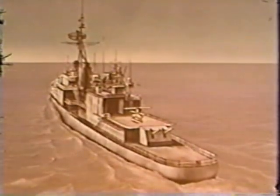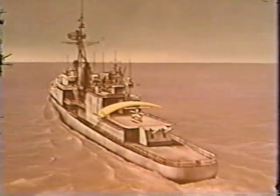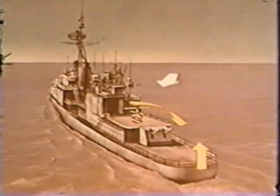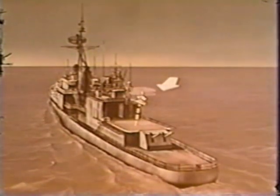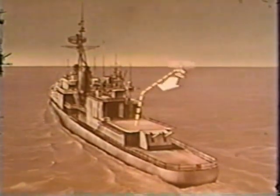Ship motion must also be taken into account during flight operations. When roll and pitch are significant, the liftoff should be made when the deck is rolling into the relative wind, and as the deck rises in pitch. The launch should begin with vertical flight, raising the drone to a safe altitude and out of significant ground effect. Translational flight should be started into the wind.